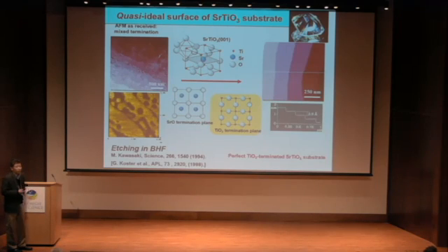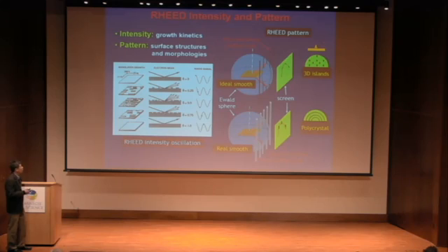We have the system for atomically controlled growth of strontium titanate heterostructures with the strontium ruthenate bottom electrode. We use a single crystal strontium titanate substrate in order to make it strain-free, so we study just the intrinsic nanopolar regions. We have a single surface termination, the titanium terminated surface. Then we grow the strontium ruthenate using RHEED control, and each layer oscillation corresponds to one unit cell of thickness. So we have very tight control of the film thickness.